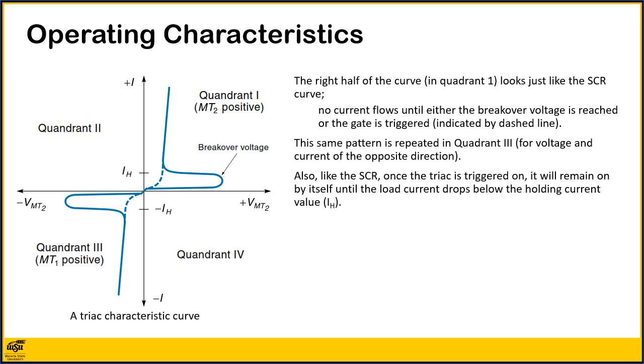Also, like the SCR, once the TRIAC is triggered, it will remain on by itself until the load current drops below the holding current IH.